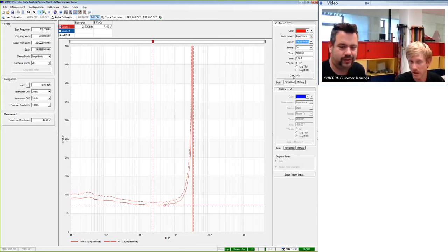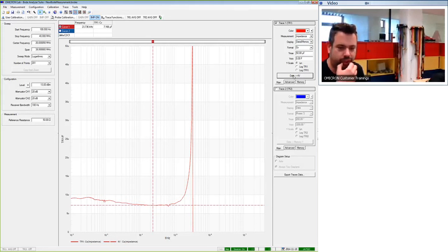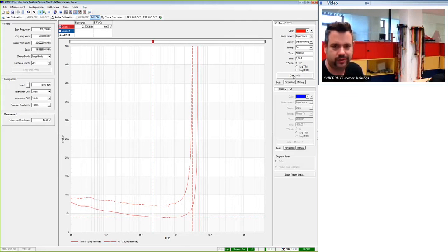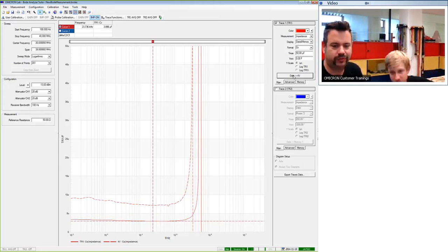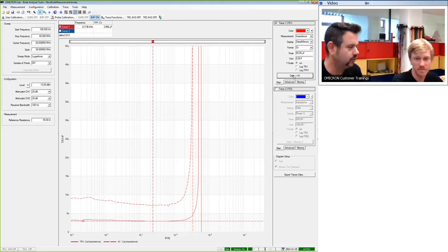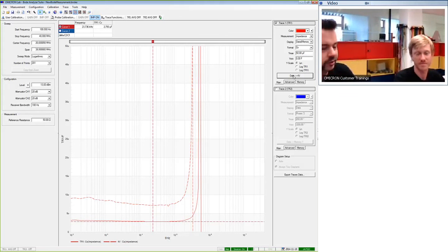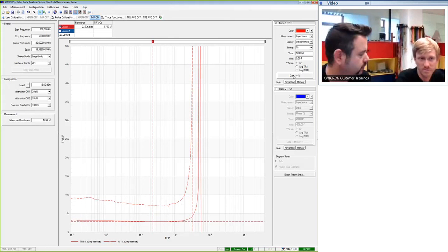That's why it had 11 microfarads, a 10 microfarad capacitor. And now it's aging. So if we increase... Yeah, let me do a new storage. So I've started now in the aged area. And now I go to 10 volts, or let's say 15 volts, which is half the nominal voltage. Yeah, it's going down. So now I'm at 15 volts, and you see, at 15 volts you only have 3 microfarads. So this is definitely something to take into consideration when you're using ceramic capacitors in your design.